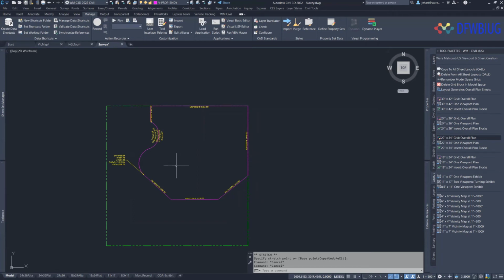Will it warn you if one of the polylines is not enclosed, like there's a 1 foot gap or a point something gap? Will it warn you, or just won't run the routine? It'll still put a length and the varying distance on the line, but that's where the integrity of good drafters comes in, making sure that lines are extended. Well, let's say you did create a label style that gave you acreage, what would happen?